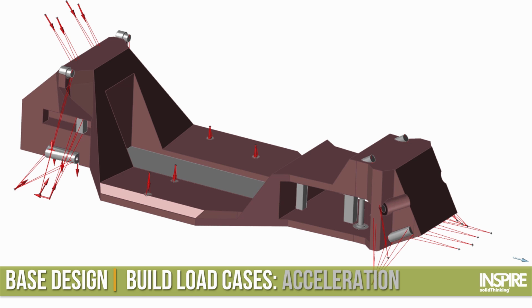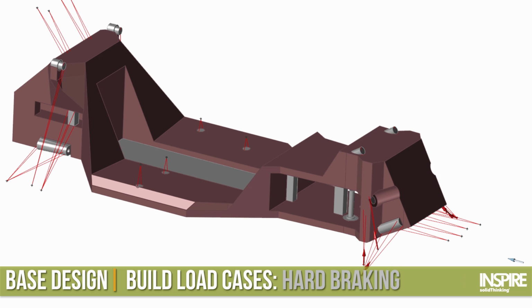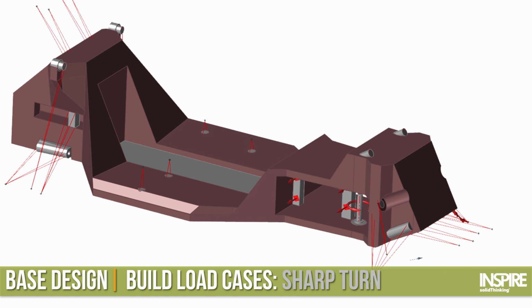So in the case of the car, I knew there would be times that it would be accelerating. I knew other times it would be decelerating. And in other times it would be doing hard turns. And so I actually created 3 separate sets of loads: acceleration, hard braking or deceleration, and sharp turns.